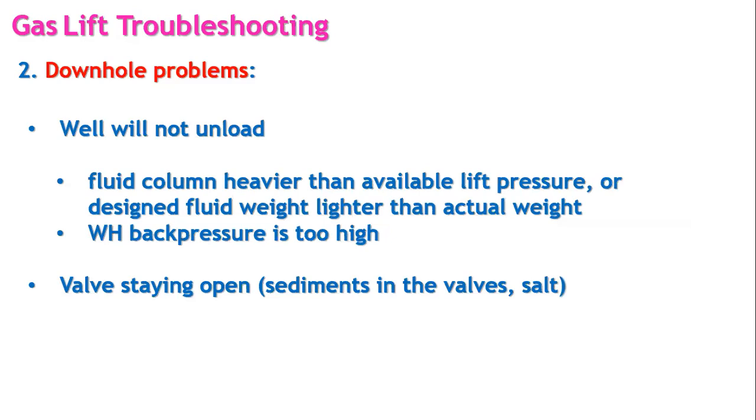So the fluid column is heavier than the available lift pressure, or the design fluid weight is lighter than the actual weight. So in this case, we are having problems. Another issue is the wellhead back pressure is too high, so we will not be able to unload the well.